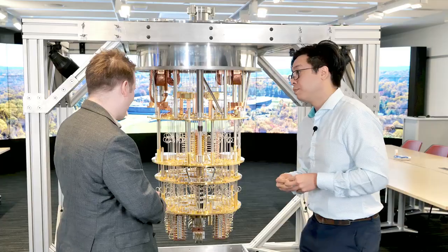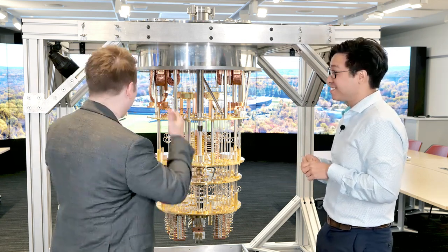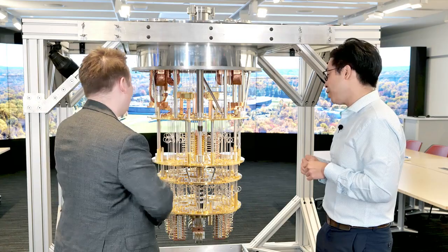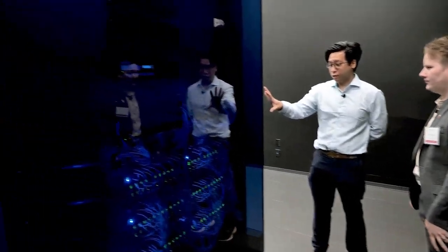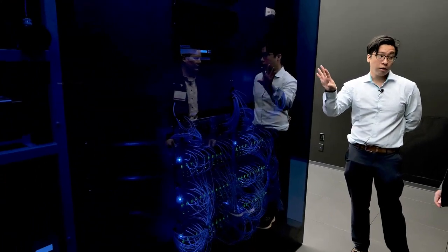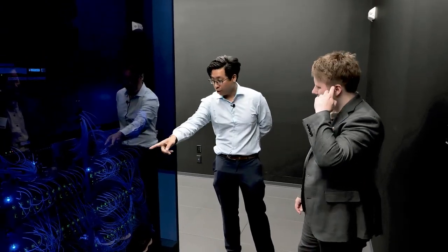Sitting at 5 gigahertz, 6 gigahertz, depending on the qubit frequencies and depending on the architecture that we have in the chip. So your qubit is controlled by a 5 gigahertz system, just to relate it. Yes. And a lot of the infrastructure for the control sits at room temperature. What you have inside the refrigerator are more of, you can think of it as, the cryogenic peripherals to condition the pulses, to make sure that they're at the right signal levels, that they're at the right noise levels, and that the signals that come out are amplified to the right degree.